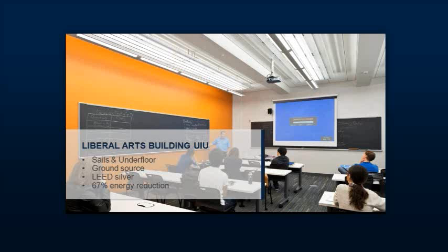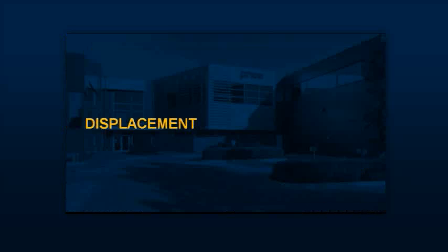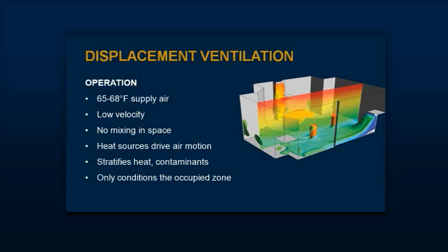The potential in the future is hybrids, I think, and water and most likely displacement will play a major part in that. So that leads me into the next product, which is displacement ventilation. The displacement ventilation component is basically supply air that is allowed to distribute itself inside the room, where on an overhead mixing system, we use the energy in the supply air, the velocity, to drag room air and mix it thoroughly. In the case of displacement, the last thing I want is any significant throw distance out of the face. Often, the diffusers are in the same location as occupants.